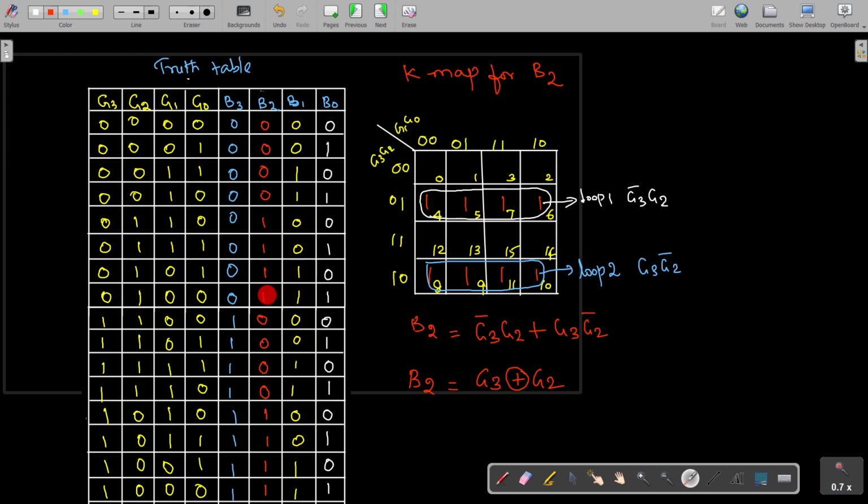Then we have this one that corresponds to 0100. So 0100 means it is for 4. A common mistake made by us is to take this as 0 value, 1 value, 2 value, 3, 4 like that, and if you try to make it into this K-map, it will end up with a wrong answer.